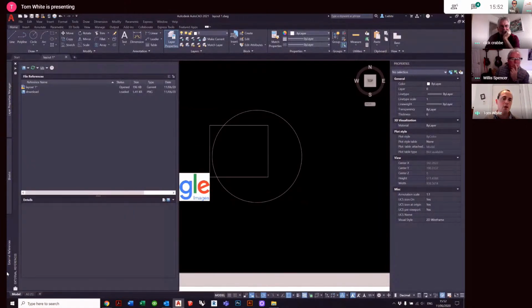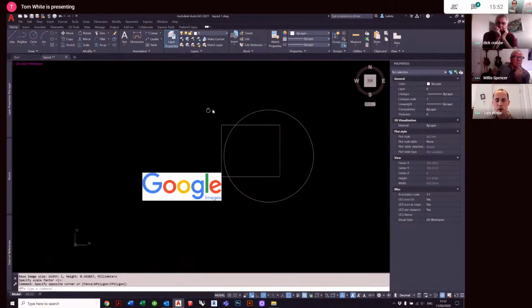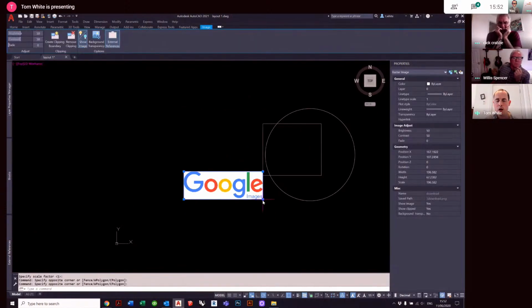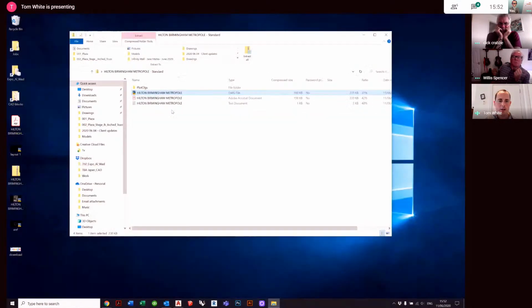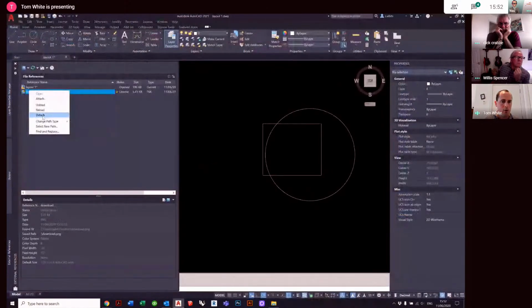So what this is, an external reference, I can right click on it. I can't bind it. So in this circumstance, I'd have to use the e-transmit. And as we just discussed, I prefer not to use the e-transmit if at all possible. What you can do is, if I erase that, and I very much hope it's going to work.